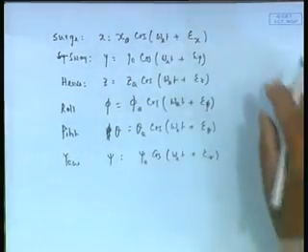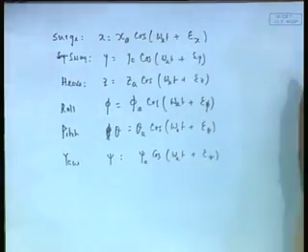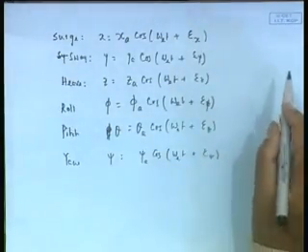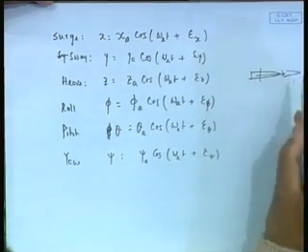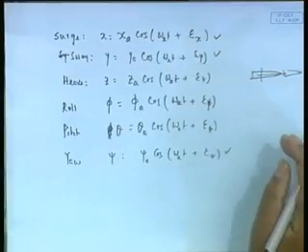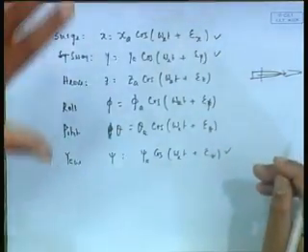Now, you see here on these modes of motion, which is important for us, that is why I wrote all this stuff. Think of this, there is a ship here, somehow it got moved forward because of a force. Will it come back? How much will it come back, etc. In the horizontal plane, that is surge, sway and yaw, I have no restoring force, that is if I push it, the hydrostatic force does not try to pull it back. So, from the point of view of motions, it becomes less important, because the ship is neutrally stable in the horizontal plane.